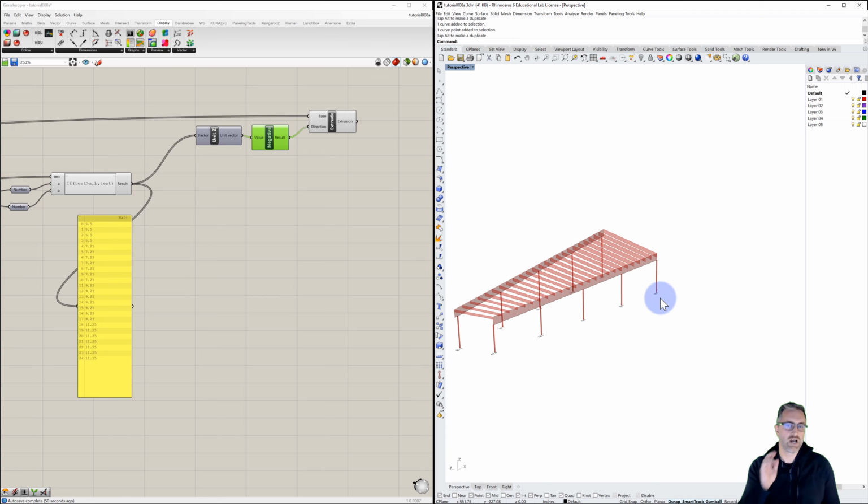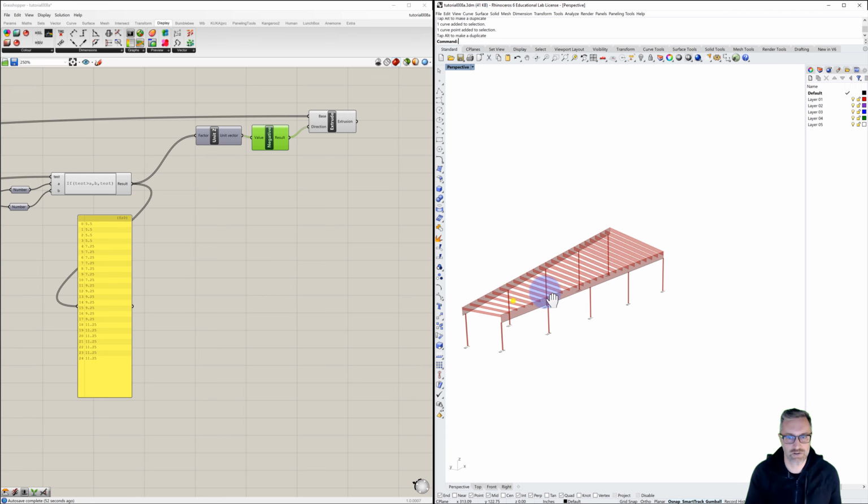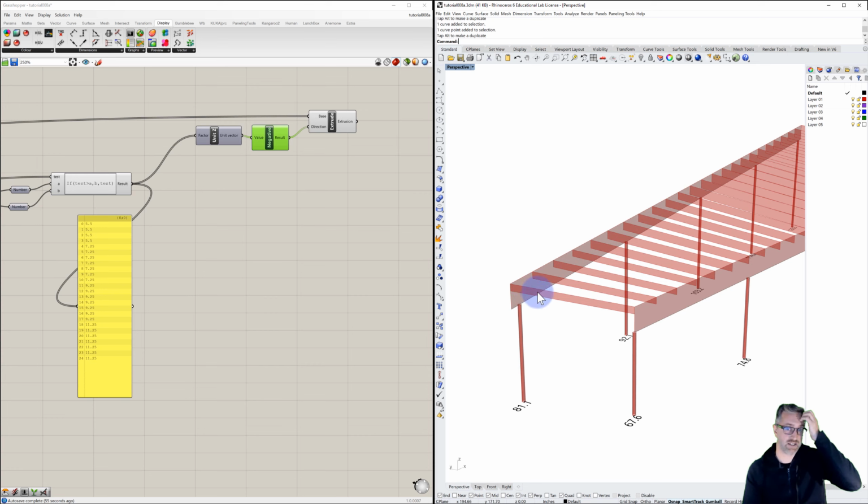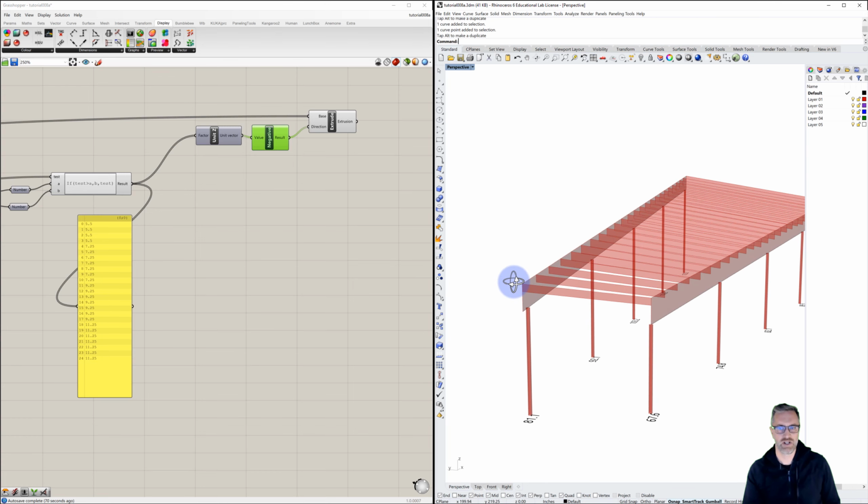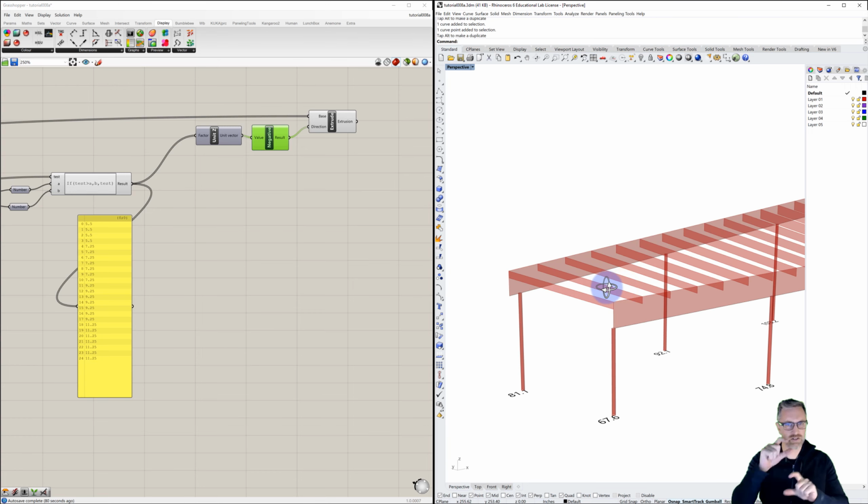And so they're all there. A couple of things are happening. So if we look at the set of relationships, our first line that we're working with sits on the top of the columns. We're extruding our girder straight up in the Z direction, a certain dimension, again, a global parameter. Then we copied our top line, and now our rafters are working from the top down. So if we were to skin this roof with plywood or with a sheathing material, it would all flush out on top of the girders. And so we just set a couple of relationships with that.